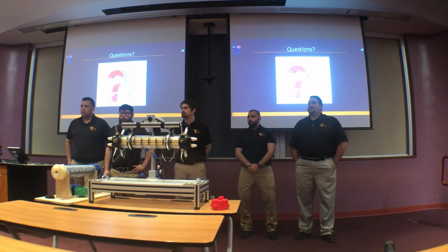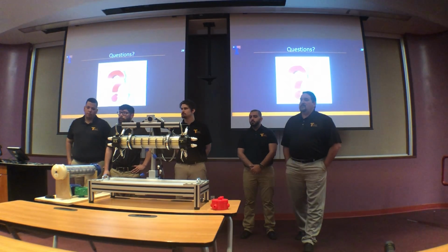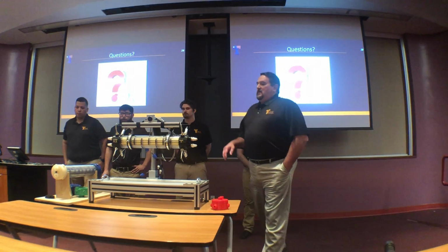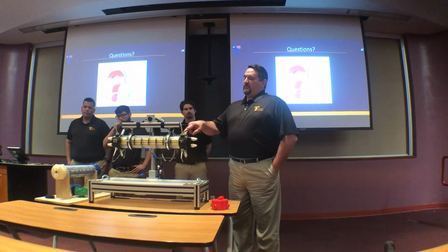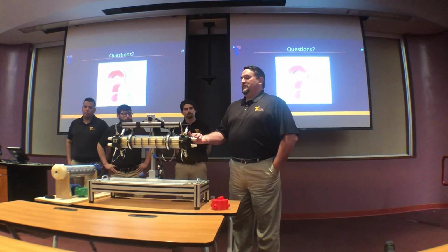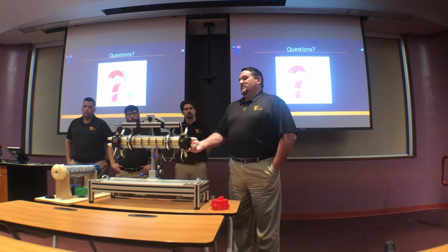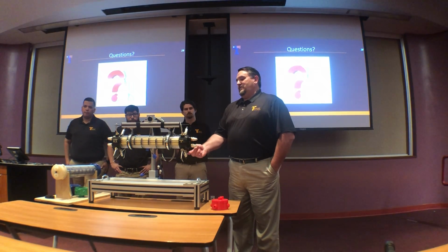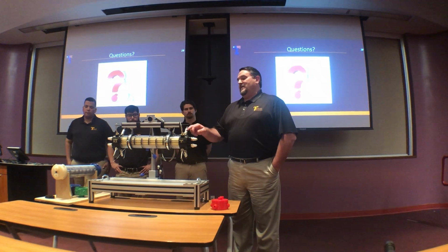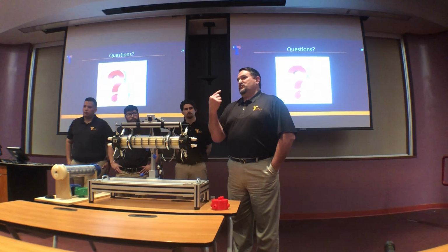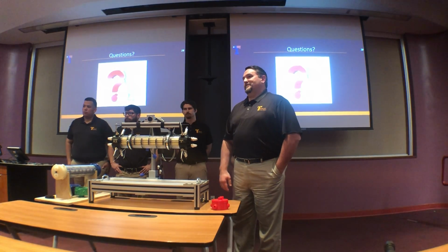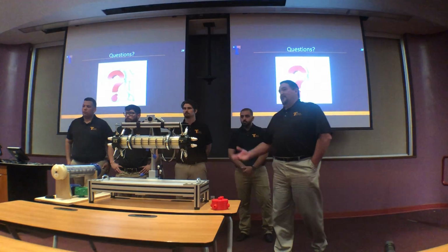How far do those probes penetrate the plenum? There's a 3/8" hole in here that leads from the inside chamber to the outside chamber. So it's kind of on the hot side. On the cold side, it's pretty much submerged in it, except for the pressure. The hot side, cold side should be fine. But this is not all the way down into the chamber. But there is a reservoir coming up that can surround the thermocouple tip, so hopefully there's enough mix and water change where you can get a reliable temperature reading. Hoping, anyway, I don't know.